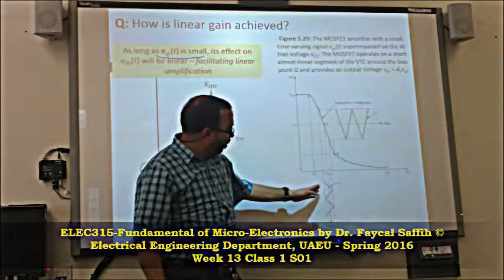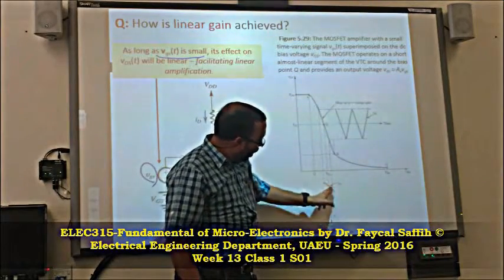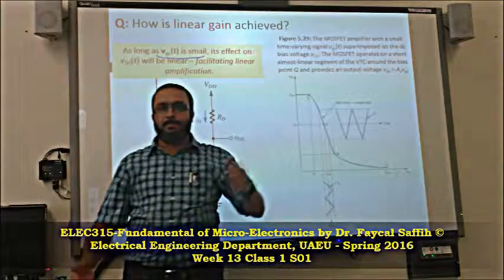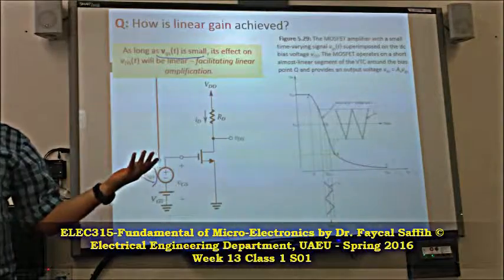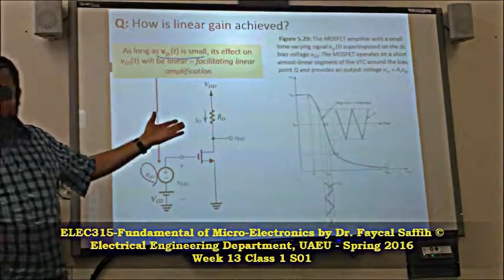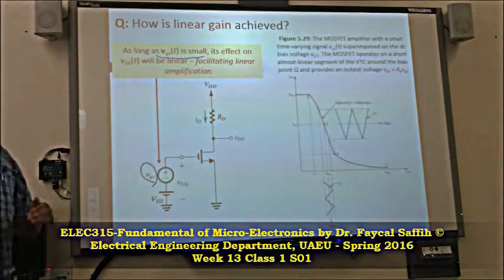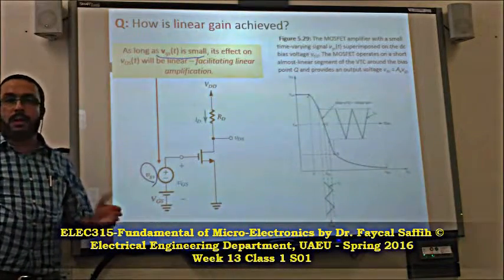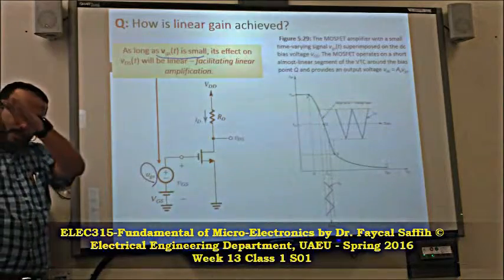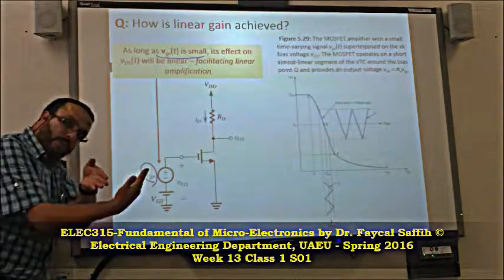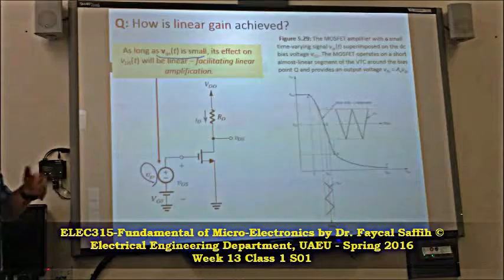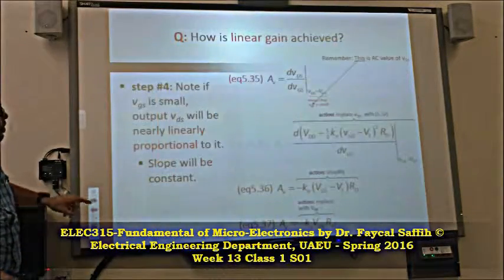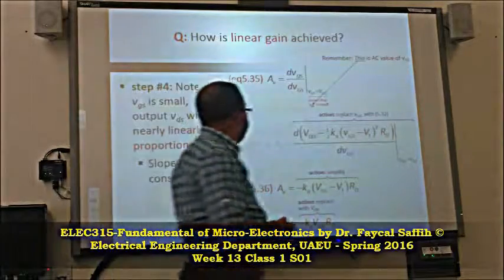And as I've told you here, when this goes up, this will go down. See here? They are inverted. It's like an inverter. Remember, we did a similar circuit last time. We found that from the characteristic, when the input is low, the output is high, and when the input goes high, the output goes low. Remember the VTC. So this is nothing new. We studied it before.